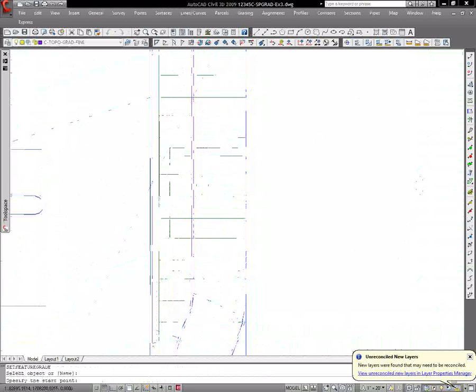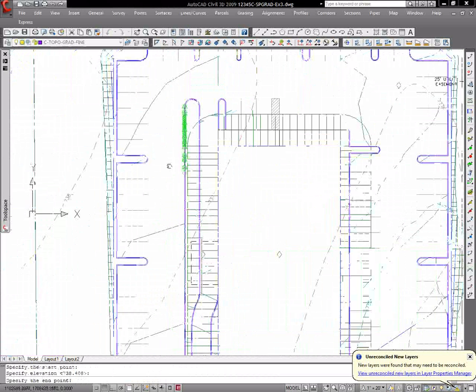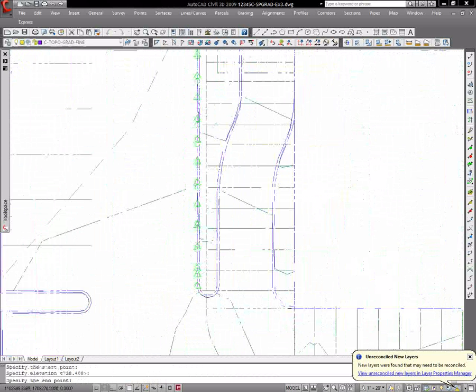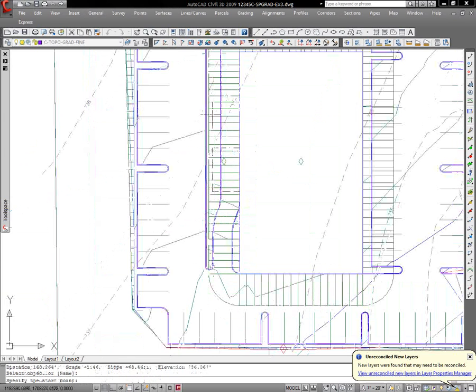We're going to start at the top. And we're going to go from this point at its elevation down to this point at whatever elevation it is, and instead of dropping steeply somewhere in the middle, we want it to just do a constant grade of what turns out to be 1.46%. And then we'll do the same thing for the top of curb feature line.